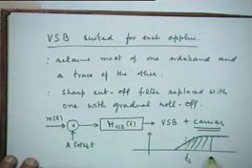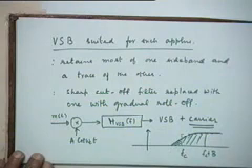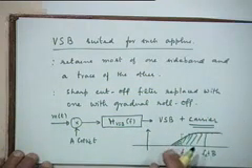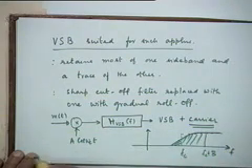So this is f_c, this is f_c plus B, but you are also transmitting this portion of the lower sideband. Right? It could be the other way around. You could be transmitting most of the lower sideband, and a small portion of the upper sideband. It could be either way. Right? Of course, the similar thing will exist on the negative frequency axis.